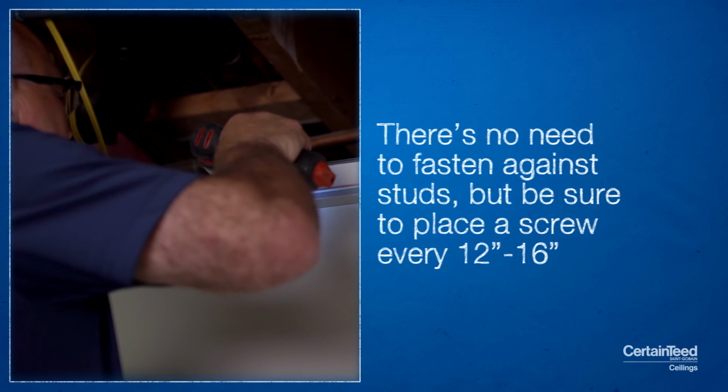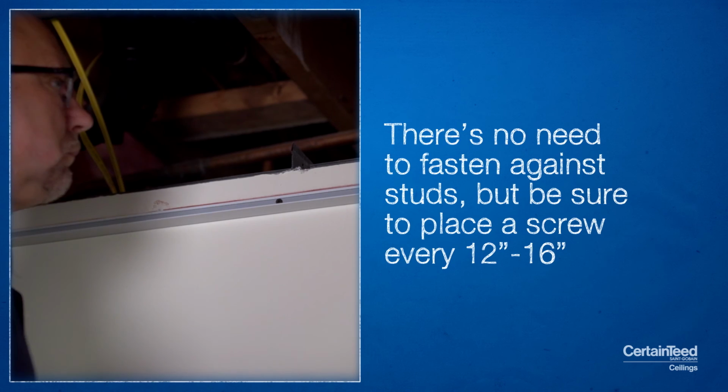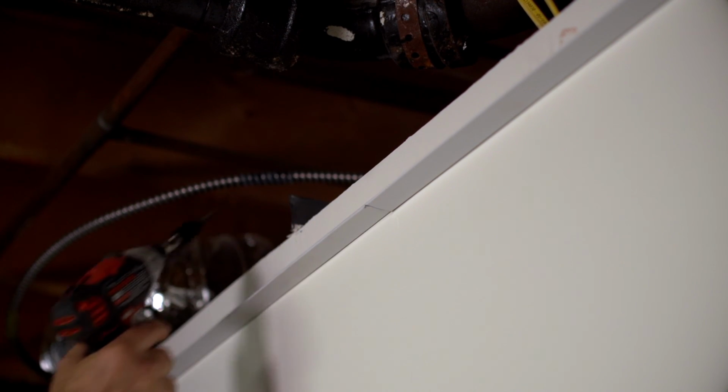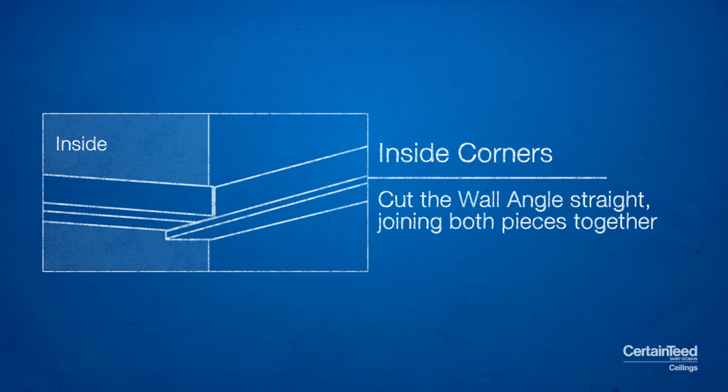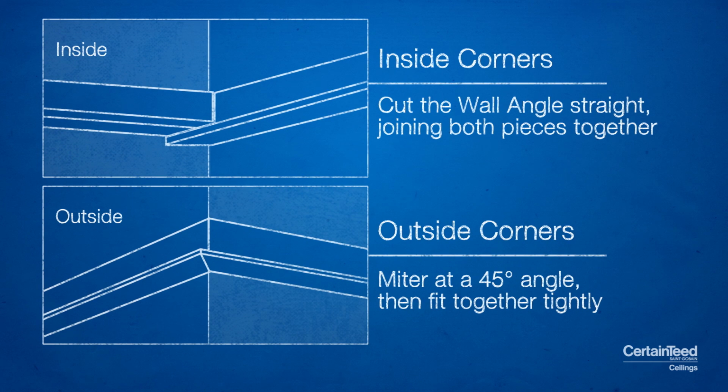There is no need to fasten against studs, but be sure that you have a screw every 12 to 16 inches. Try to butt the factory ends to each other and use the cut ends at the wall intersections. When you get to an inside corner, cut the wall angle straight and join them together. For outside corners, you will need to miter them at a 45-degree angle and fit together tightly.